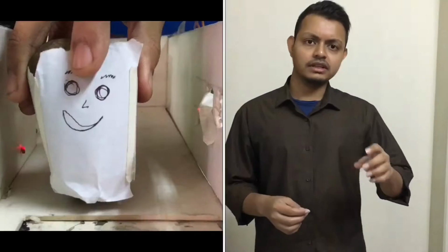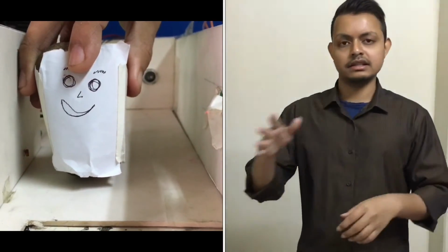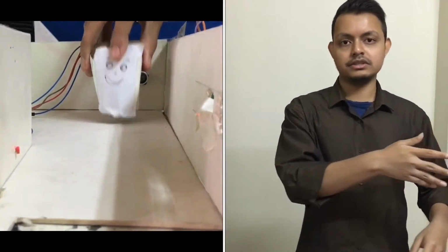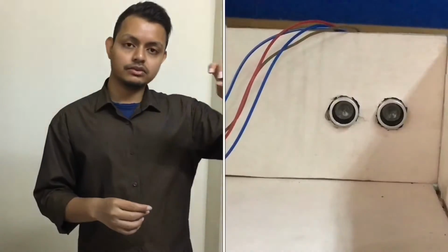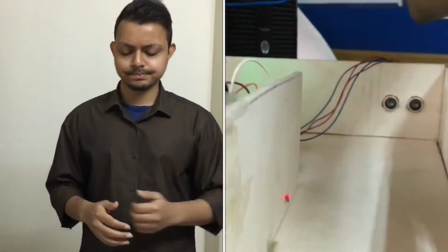During an entry, the laser is blocked by the person entering, and the LDR's value drastically changes. As the person moves forward, the sonar's value changes. The order in which this happens is important because during an exit, the opposite happens, meaning that the sonar's value first changes, followed by the LDR's.